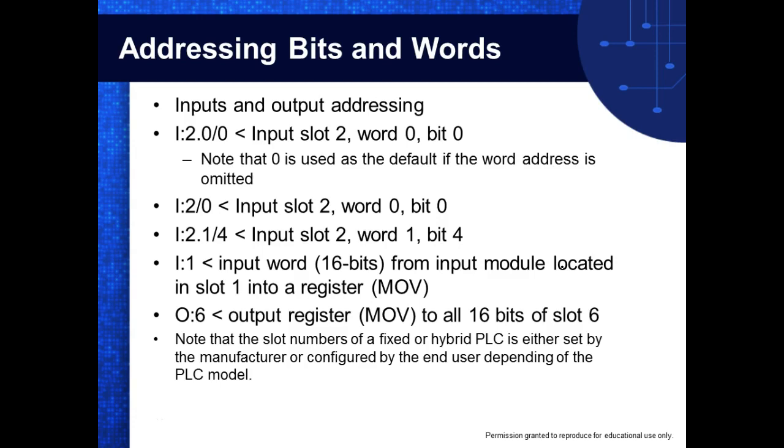Everybody okay? Our PLCs are fixed PLCs, so the CPU doesn't have to occupy a slot number. We don't have a slot number for the CPU, so we start with 0, right? You put 0, and then from then on it's assumed. Everybody okay? That makes sense. So we don't have to specify slot numbers, unfortunately.